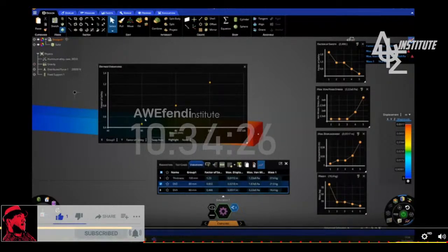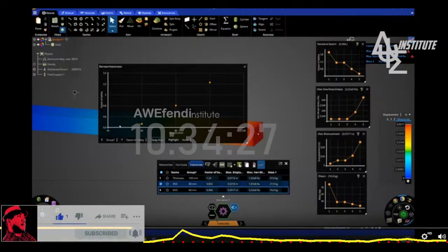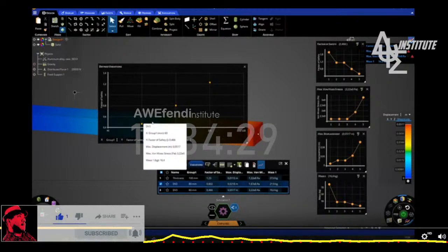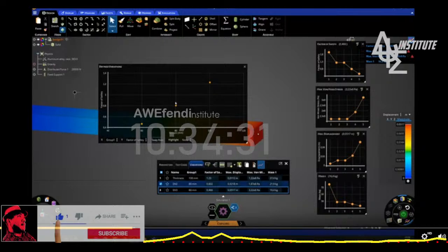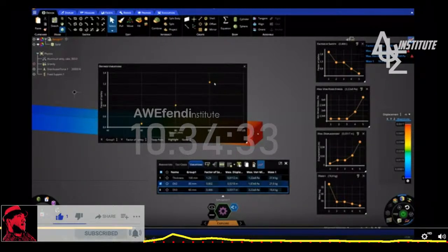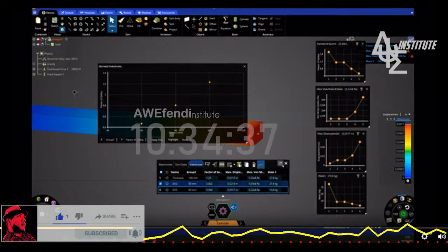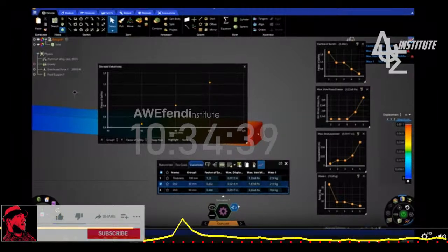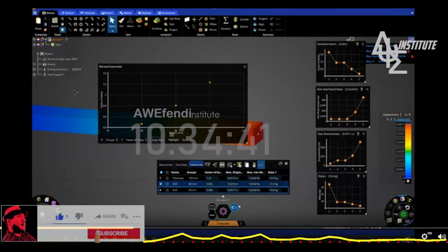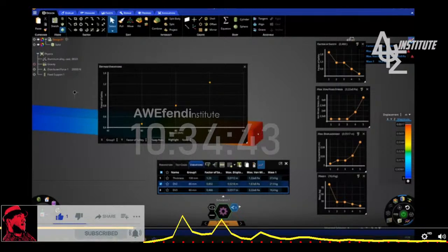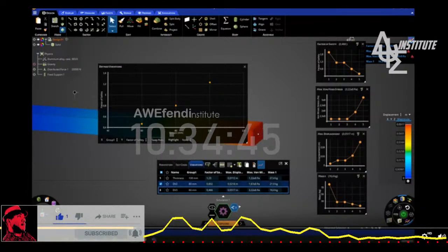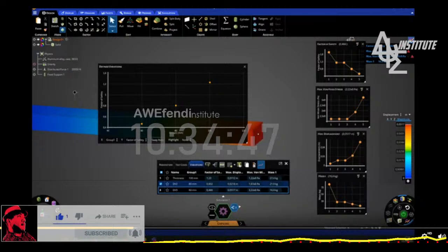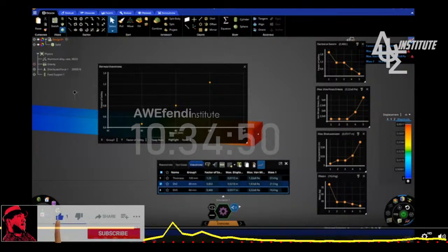At 60 millimeters, the factor of safety is below 0.6. And as the thickness increases, the factor of safety also increases, which makes sense. So this parametric analysis feature of Discovery that we have can be very useful in teaching students the effect different variables have on the results or the design of the model.